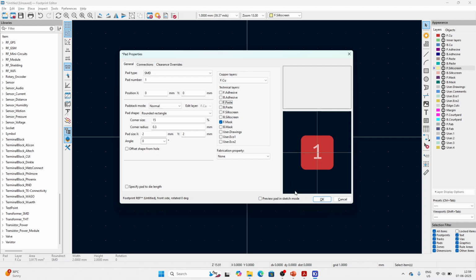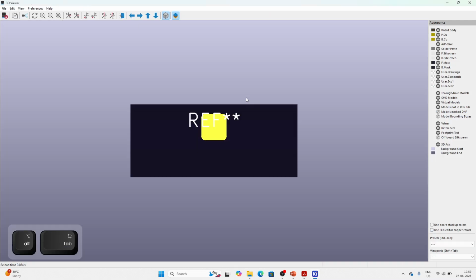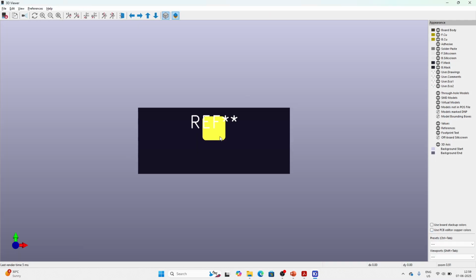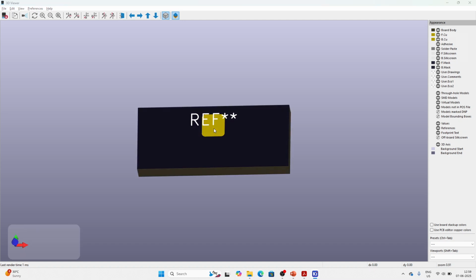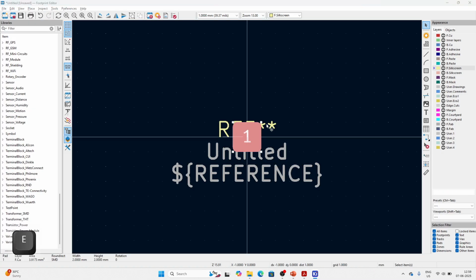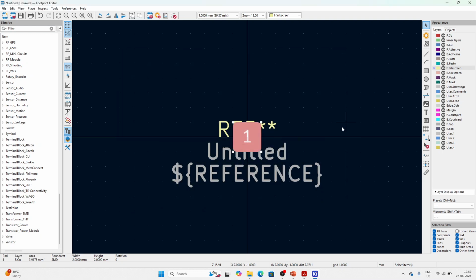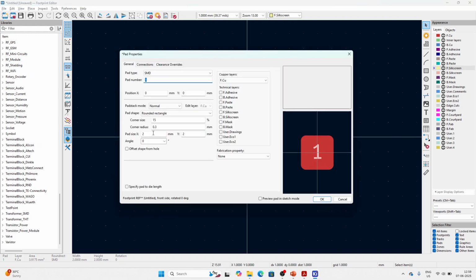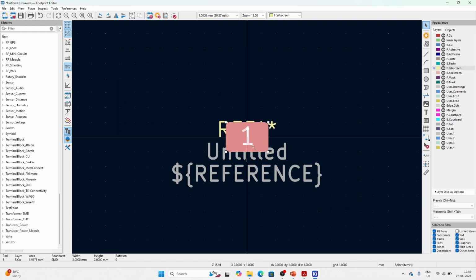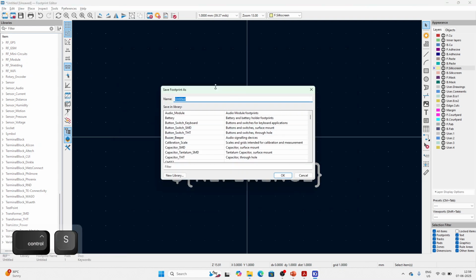If I just enable F mask, it looks like this. I don't require this mask either. The PCB solder mask needs to be on top of it, so I'm just creating it like this. This is 2 mm by 2 mm, or I can make it a bit bigger. Let's make it 3 mm by 2 mm. Okay, this looks good. We can save this.